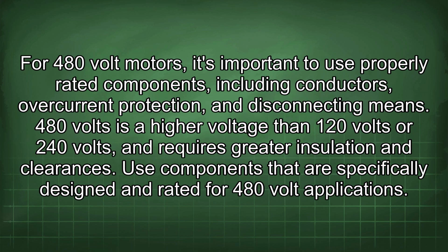For 480-volt motors, it's important to use properly rated components, including conductors, overcurrent protection, and disconnecting means. 480 volts is a higher voltage than 120 volts or 240 volts and requires greater insulation and clearances. Use components that are specifically designed and rated for 480-volt applications.